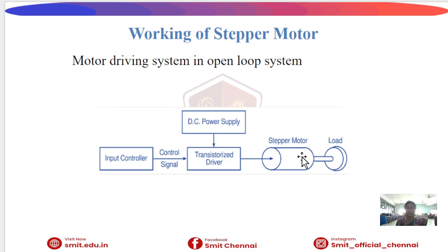So the controller does not check whether the motor actually moved or not. This system is simple and low cost, but accuracy may reduce if the motor misses the steps.